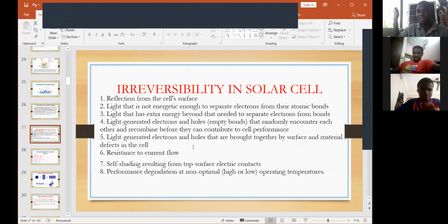So this panel is about 1 meter square. Mr. Ben, you were with us at the beginning of this class. We said the solar constant is 1,000 watts per meter square. What does that mean? That this panel should give us 1,000 watts, if we know simple mathematics, is it not true? But conversely, it is giving us 100 watts. That shows it is 10% efficiency.